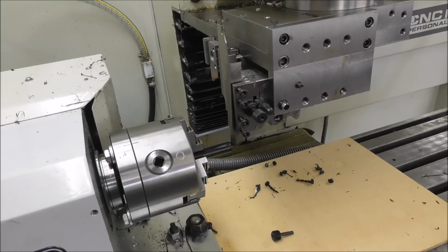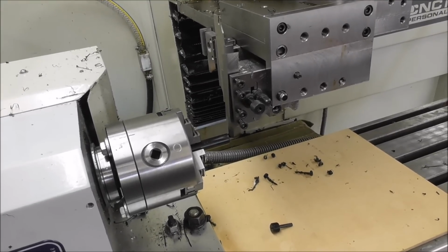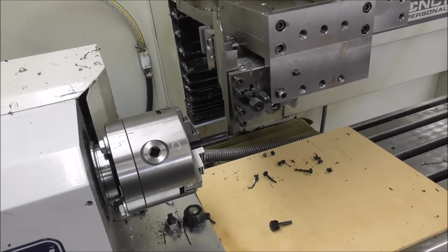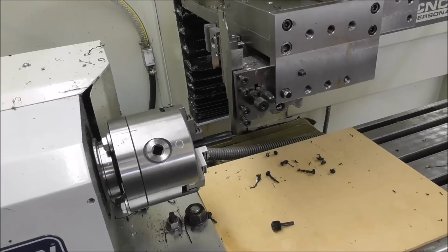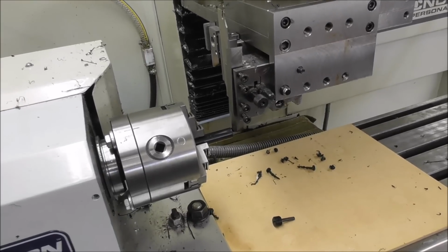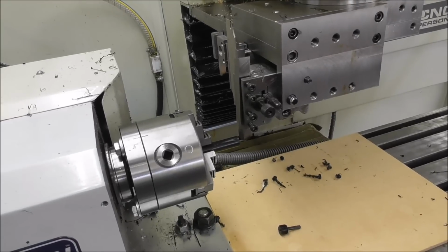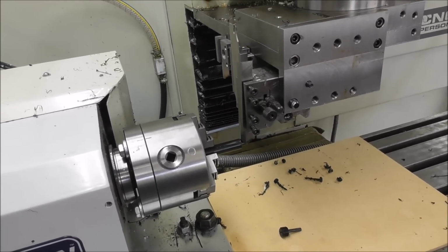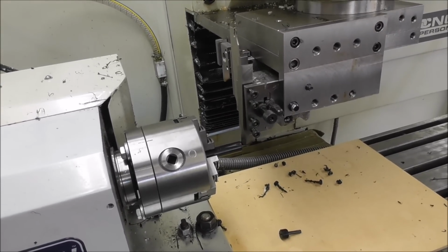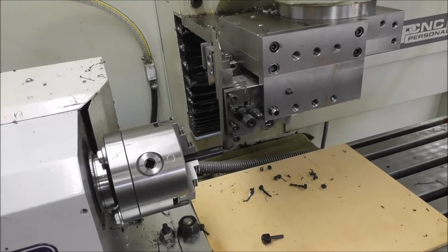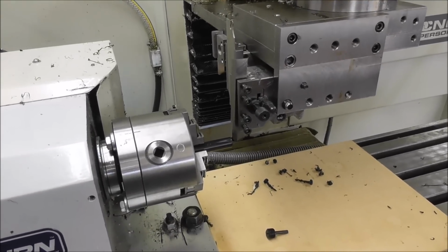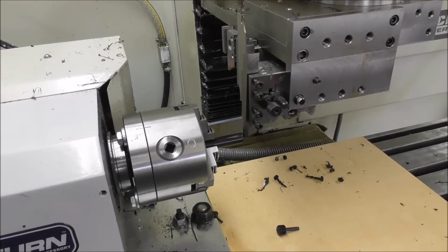When we come to the threading, you'll see that I can slow it right down even during the threading, and it won't lose its pitch. That's the great thing about this PathPilot Rapidturn system. You really can't go wrong by slowing down that maximum velocity slider. So I'll just run it now and see if you can see me slowing it down and speeding it up.